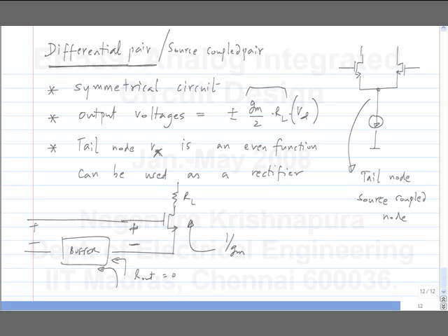So we have used a buffer, but it's not an overwhelming buffer. I mean, its output resistance is not much lower than that of the load. In fact, it's exactly equal. So there is a voltage division of half. If you apply V, only half the voltage appears here. So from this voltage to the output current, it is still Gm. But from the actual input voltage to this current, it is Gm by 2. Okay? That's all. We will see this in various different ways. Any questions?